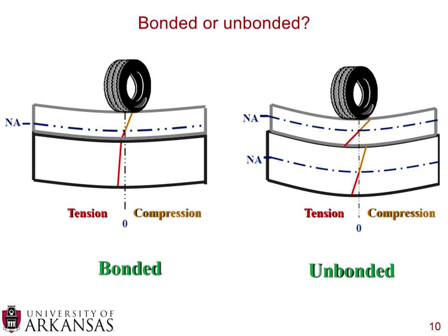Above that neutral axis, closer to the road, you have compression in your pavement structure, and below that neutral axis you have tension, and you can see that the tension transfers through that bond into the lower layers, and it keeps on going in tension. Now, because they're different thicknesses, you have a different slope, but the tension is transferred because it's a bonded surface.